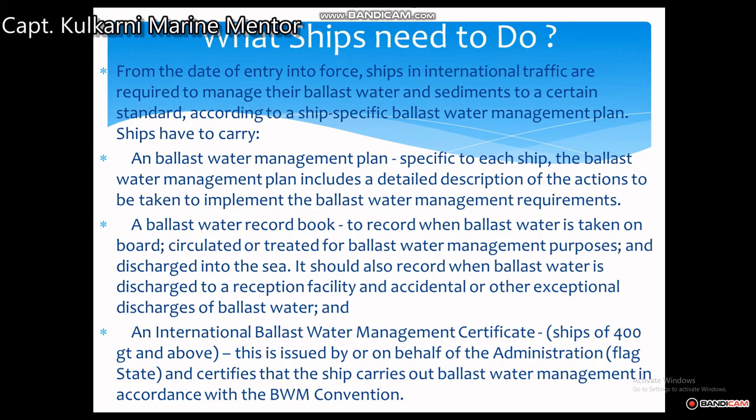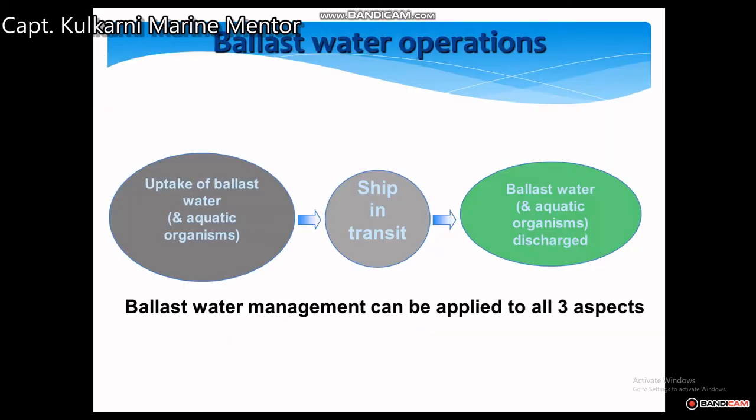Now, this ballast water operation, where exactly is it working? Uptake of ballast water: when we are uptaking it, that time we are getting these aquatic organisms. So we have to make sure that whenever we are taking the ballast water, what precautions need to be taken. Second is, in case the ship is in transit, when the ship is moving, that time we have to change the ballast, which is for the existing ships.